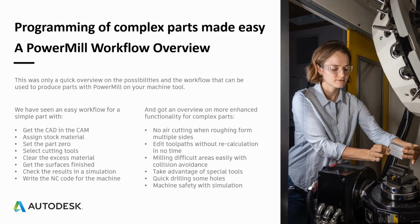For the second part, which was a little bit more complex, we did the same workflow, but with some other tools. So we used roughing from multiple sides together with the rest model or the stock model to avoid air cutting. We edited toolpaths without recalculating to save time. And we milled difficult areas very easily using collision avoidance. Collision avoidance is a 5-axis strategy, which we also use to utilize special tools and take advantage of them. After that, we made some quick holes and drilled them into the part. And to be sure that this will run on the machine, we made a machine simulation.